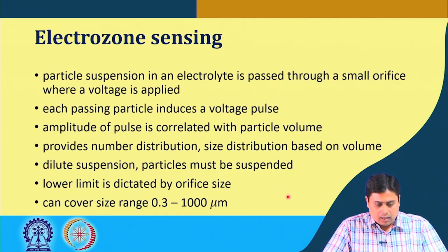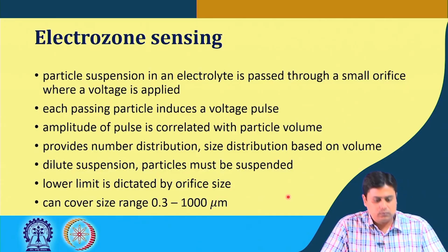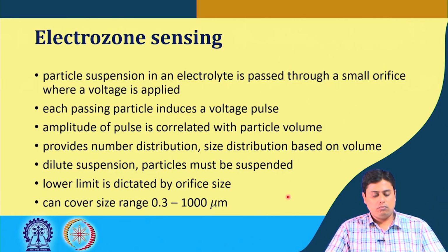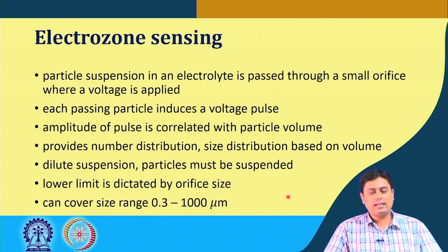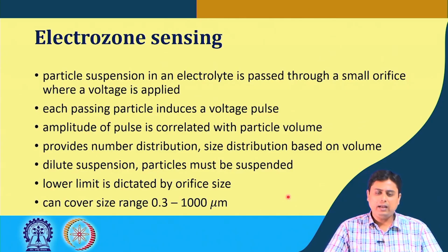The next method we will discuss is electrozone sensing. Now, in this case, the particle suspension in an electrolyte is passed, or let us say is withdrawn, through a small orifice where the voltage is applied across the electrolyte and that withdrawing chamber.